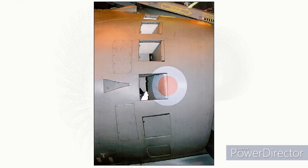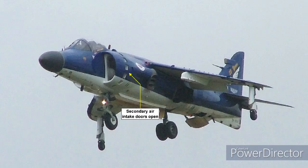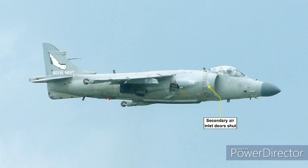To allow in more air to satisfy the engine demands, up to 16 auxiliary air intake doors have been fitted just behind the lip of the main air intake. At airspeeds below which ram pressure recovery can be achieved, the auxiliary air intake doors are held open by the depression in the intake. At higher forward speeds, when the pressure in the intake is greater than ambient, the auxiliary air intake doors are shut by the pressure differential which has been generated.